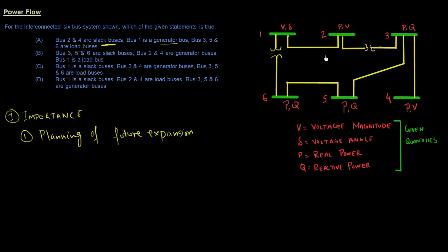A load flow study or a power flow study allows us to see whether the new load that's being connected can be connected safely to this existing system, whether there is sufficient generation on the system, whether we need to have two feeds going in, if there's a transformer, what kind of transformer taps we would need, and things of that kind. It'll allow us to answer on any of the future expansion that we're planning on the existing power system.